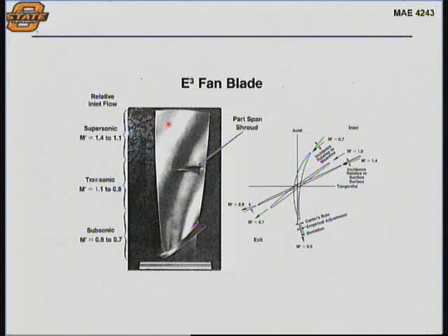So the W flow vector component can go anywhere from 0.7 to Mach 1.4 from the hub to the tip. Because of that, and because the relative velocity will change, since U is going to change from this radius to that radius, that's going to change the angle of incidence. That's why fans, compressor blades and turbine blades will have different geometric angles of incidence. The so-called stack is going to be different, and the thickness is going to be different.